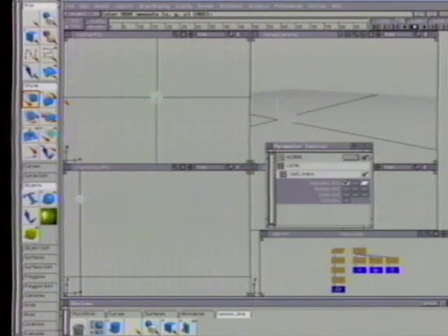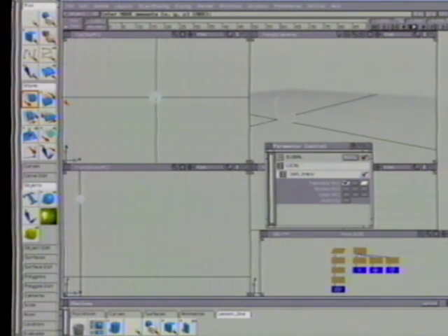Having set the translation of the ball, you will now scale the ball every time it hits the ground plane. You will use the ball scale node to animate the scaling. Because you grouped with the pivot point at the bottom of the ball for the ball scale node, the ball will compress to this point, maintaining contact with the ground plane.